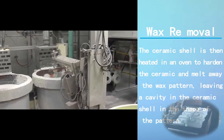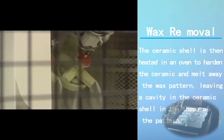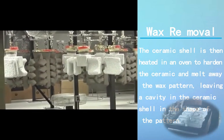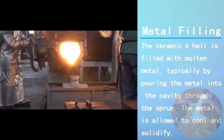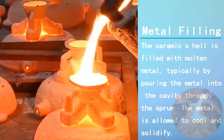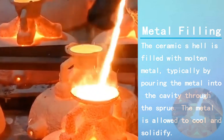Wax removal. The ceramic shell is then heated in an oven to harden the ceramic and melt away the wax pattern, leaving a cavity in the ceramic shell in the shape of the pattern. Metal filling. The ceramic shell is filled with molten metal, typically by pouring the metal into the cavity through the sprue. The metal is allowed to cool and solidify.